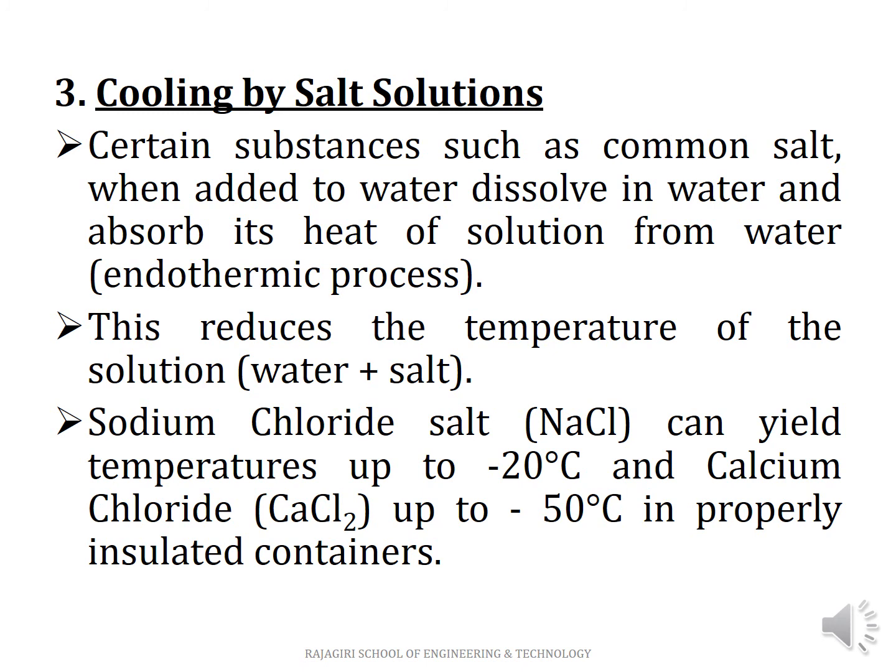The other natural method of refrigeration is cooling by salt solutions. Certain substances such as common salt, when added to water, dissolve in water and absorb their heat of solution from the water, because the dissolving process is an endothermic process. So it absorbs heat from the water, and this reduces the temperature of the water-salt solution.